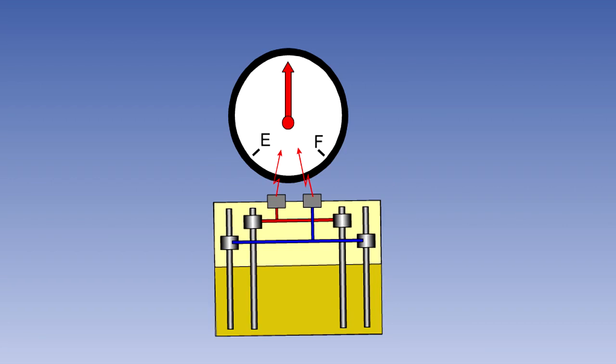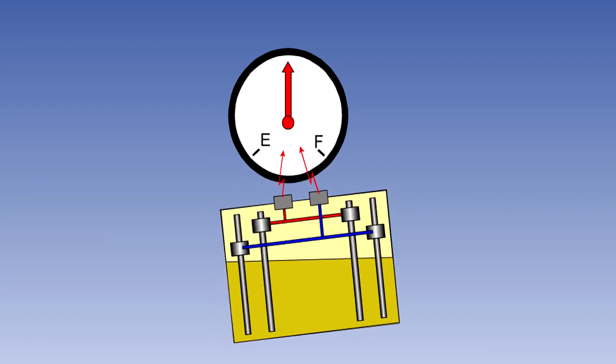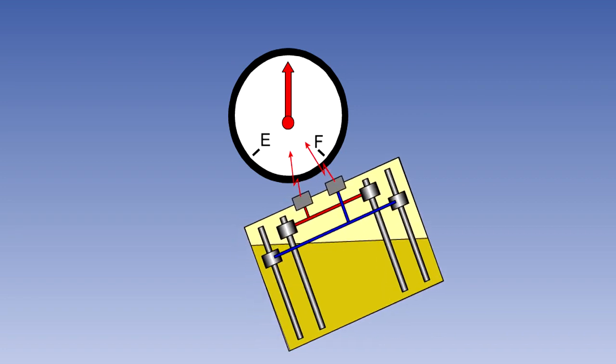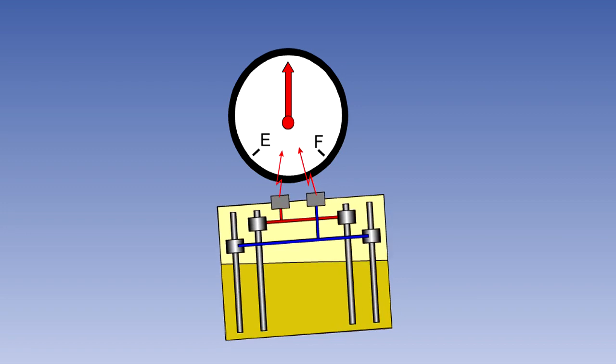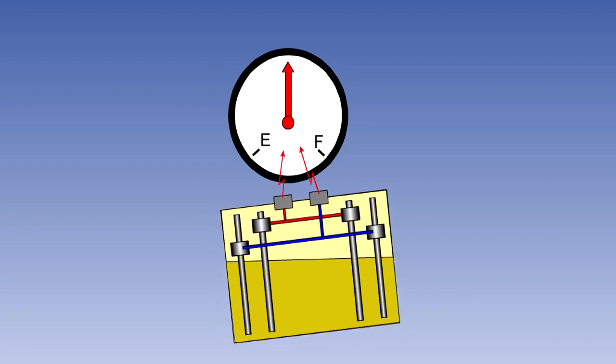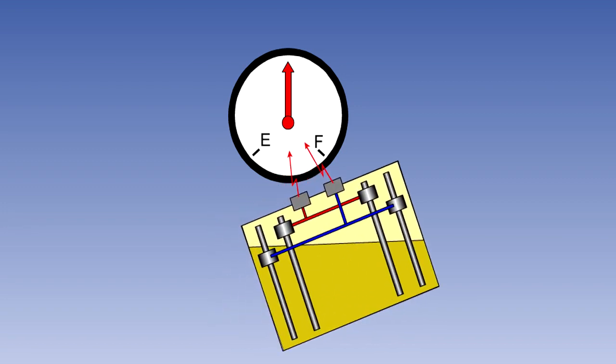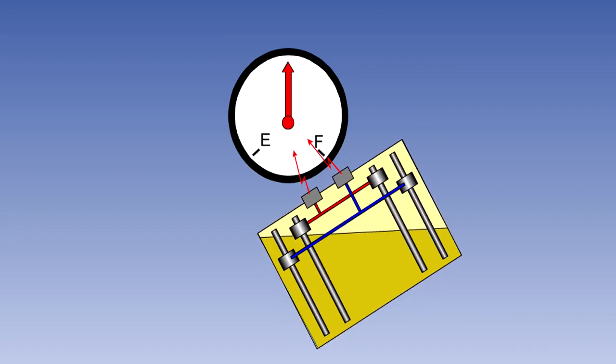To compensate for changes in attitude, the capacitive system has a number of capacitor probes in the tank connected in parallel to average the measurement of the fuel in the tank. In this way, as the attitude changes, a fuel level increase is sensed by one capacitor and a decrease is sensed by another. This enables the system to give an accurate indication irrespective of the aircraft attitude.